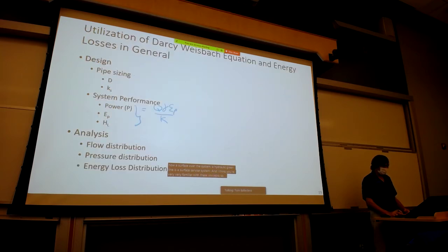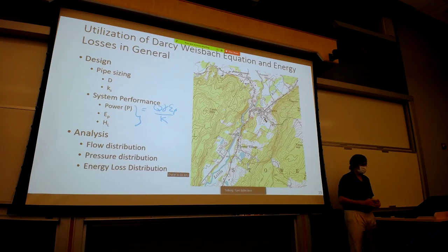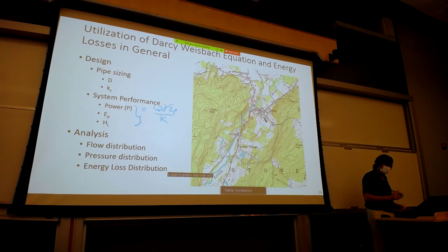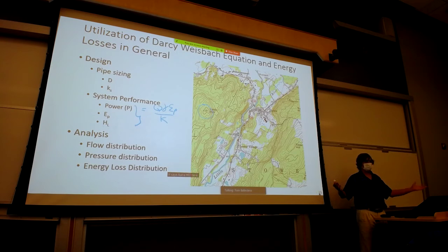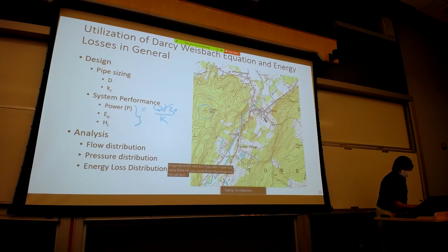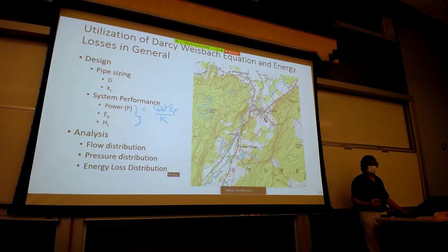So, there it is. On the right is a topographic map over in Vermont. And on this topographic map, I think it should be obvious to you, it says Katy Hill here, but if you didn't have that name, you should see that the contours go from 1,000 here, 900 here, and then at the very top it's 1122. So you know you're going uphill.